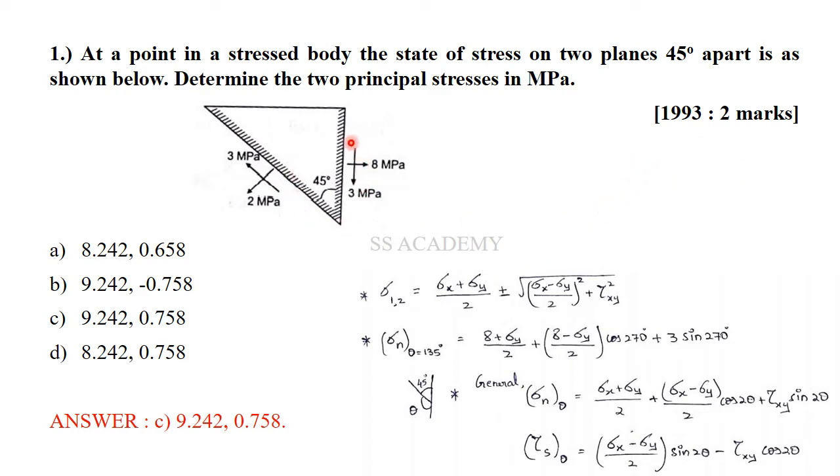Here you can see, since there is a shear stress on the x face in the y direction acting clockwise, this normal stress can't be a principal stress. The actual definition of principal stress is that there should be no shear stress. So we have to find the principal stresses from the given data.